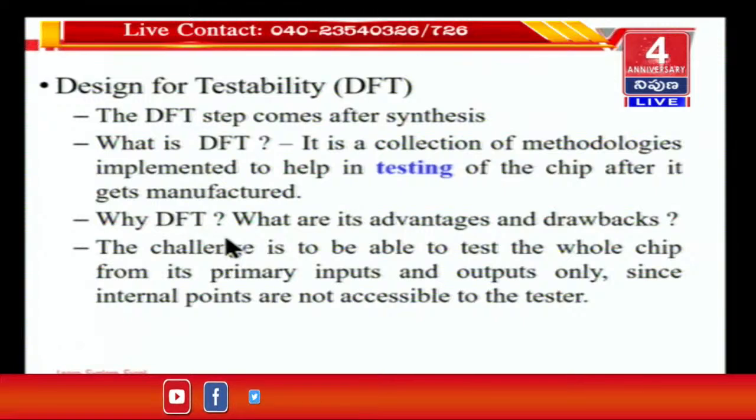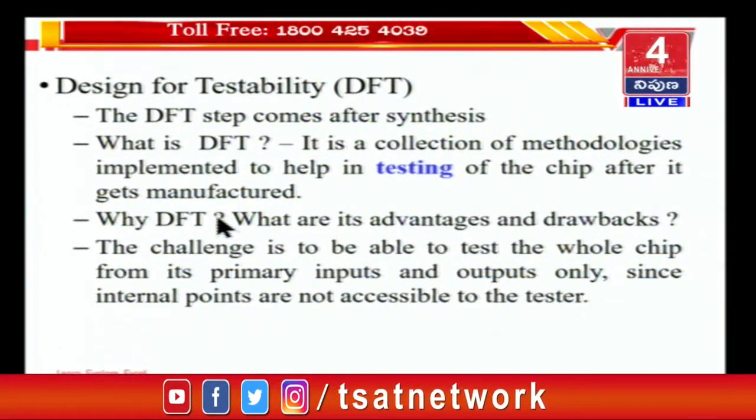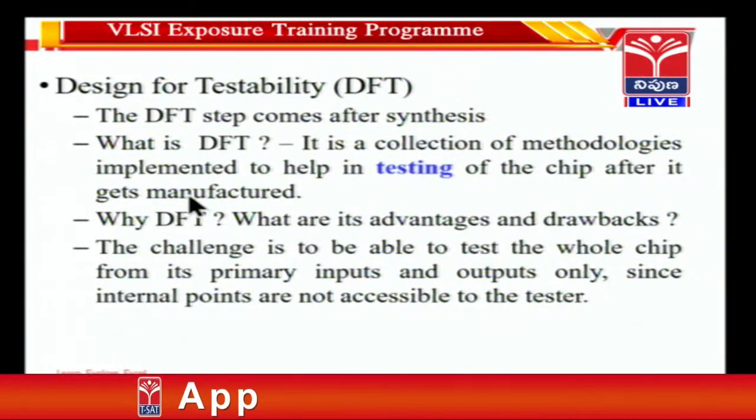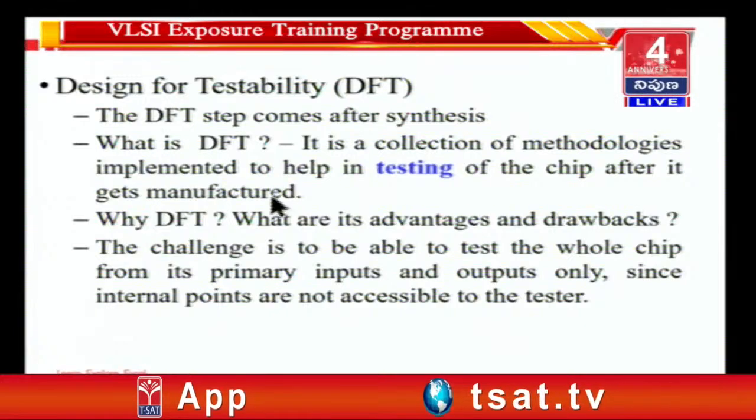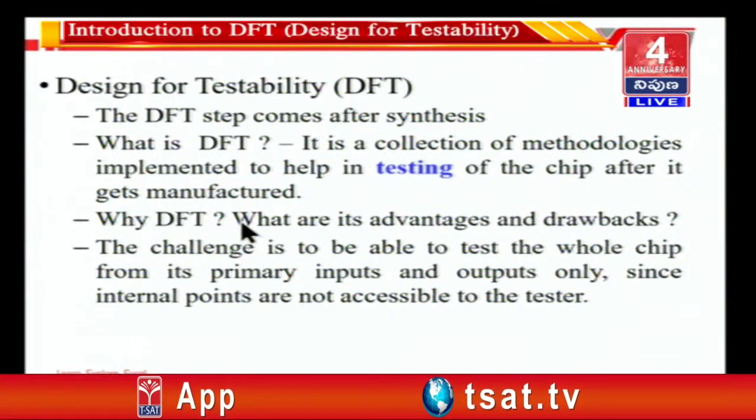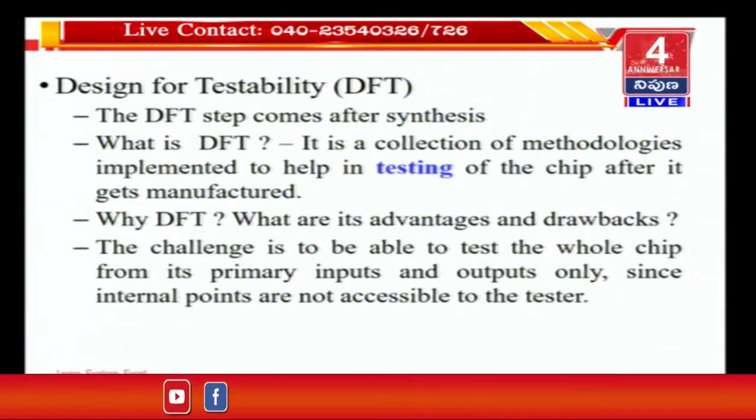So there are different kinds of faults or defects that need to be checked when the chip comes back from manufacturing, and DFT is a collective name for a few methodologies, maybe 4 or 5 or 6 different methodologies, which are used to modify slightly the chip circuit, not in the functional way, but for making it easy for testing.